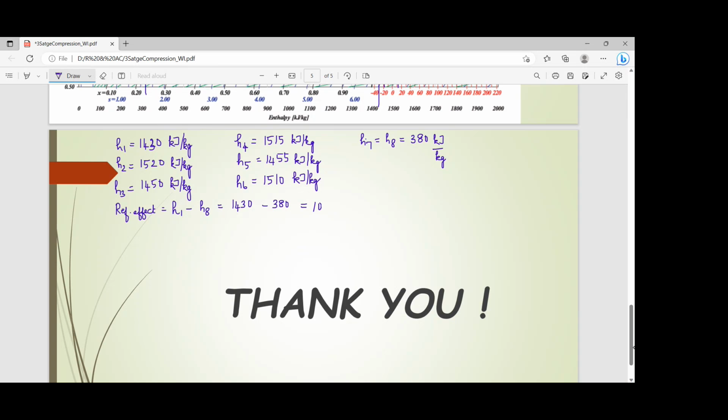Okay, so this is 1050 kilojoule per kilogram. And we already have the refrigeration effect as 10 ton of refrigeration, which is 35 kilowatt, which is kilojoule per second. So the mass flow rate is 35 kilojoule per second divided by 1050 kilojoule per kilogram. So this would give me the mass flow rate in kilogram per second.